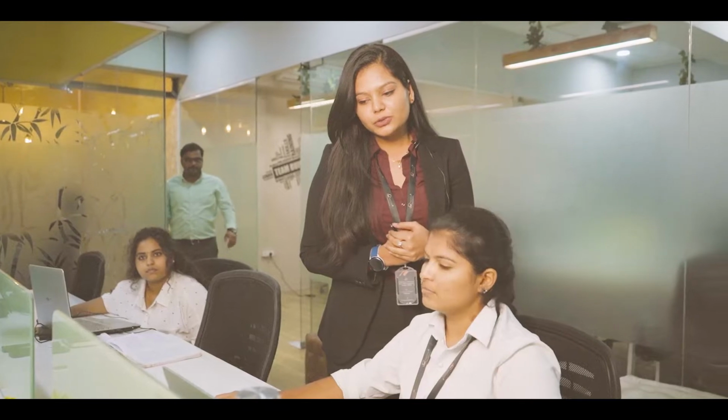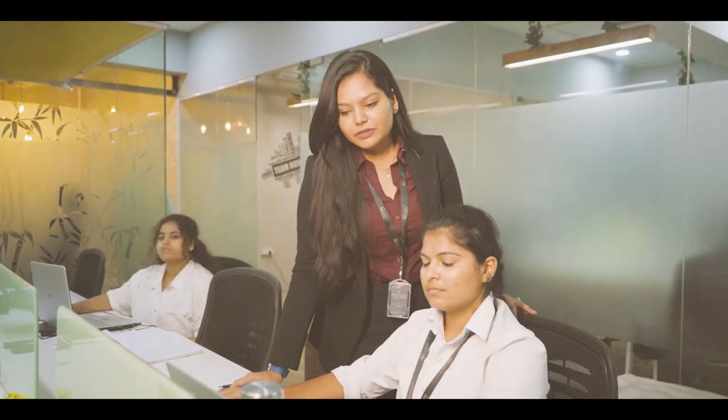Soil testing will be done to determine the safe-bearing capacity of the soil. Using the safe-bearing capacity of the soil, the structural team will work on the structural drawings, and depending upon the guidance given by the report, we will determine the depth of the foundation and the type of foundation used in the project. So I request Abhida to show some of the soil reports we have given to the clients.